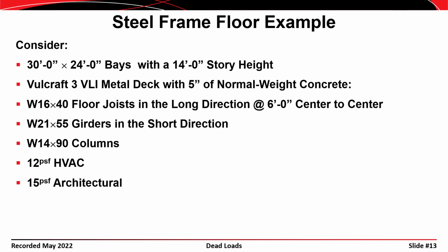Okay, let's take a look at an example problem. Let's assume that we have a structure that has 30 foot by 24 foot bays and a story height of 14 feet. Let's suppose that we have Vulcraft 3-inch VLI metal decking with 5 inches of normal weight concrete. We have W16x40 floor joists spaced at 6 feet center to center.